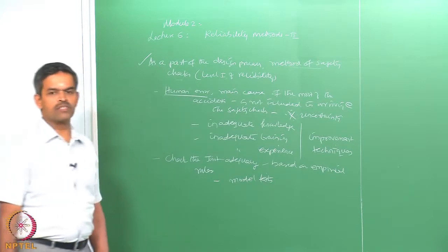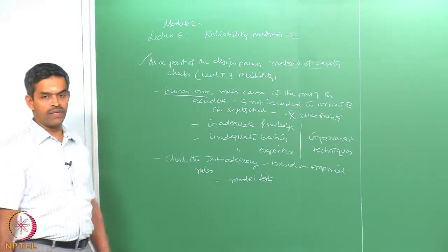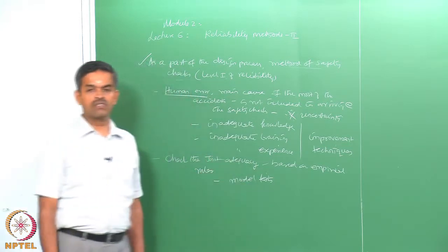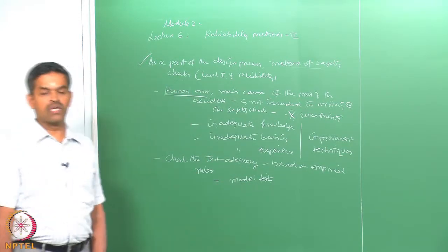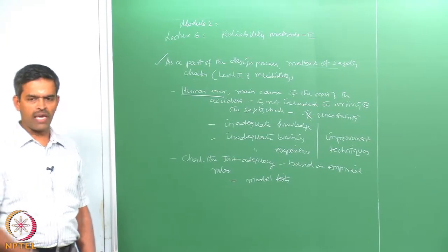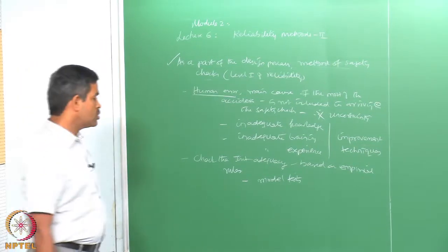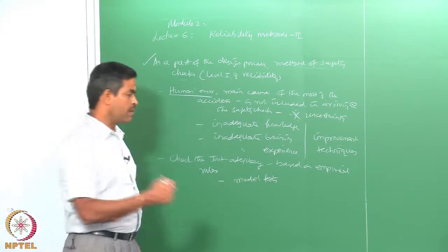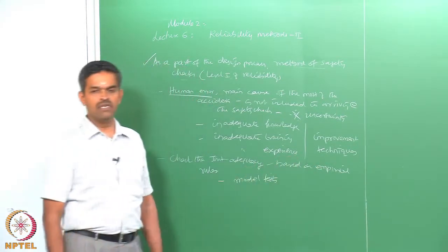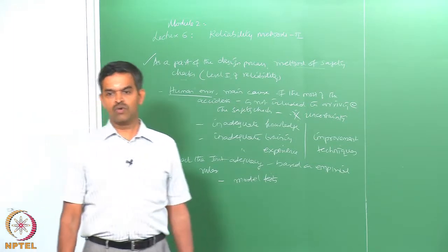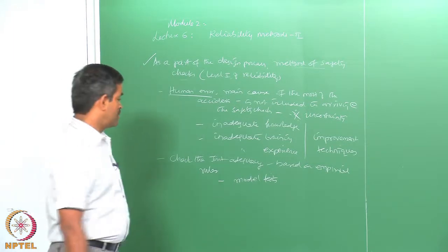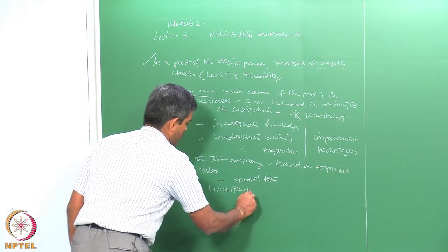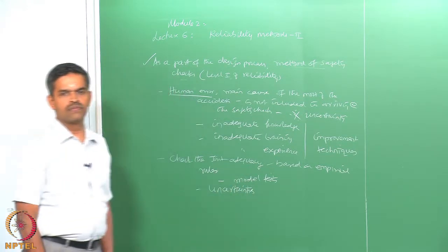I will show you later in this module one of an application study what we did, where the inferences derived from the model test for stress concentration factor, the load carrying capacity of tubular joints, maybe K, L, T, etc., show a different significance compared to the ones derived based on the so called empirical studies which are referred back in the literature. So, even then this will lead to lot of uncertainties.